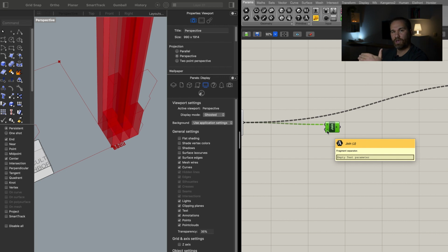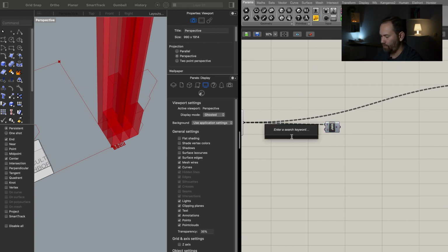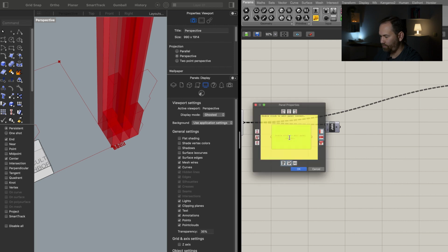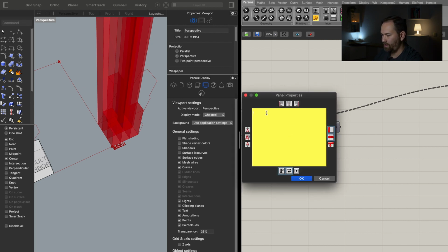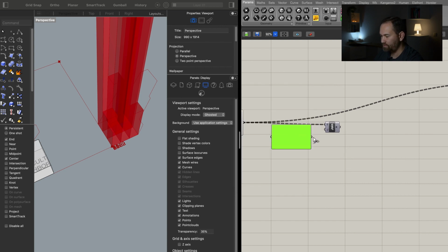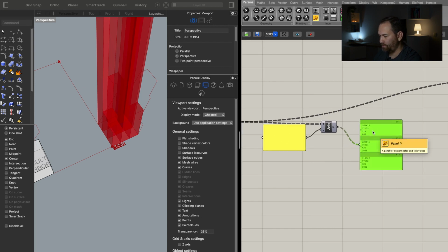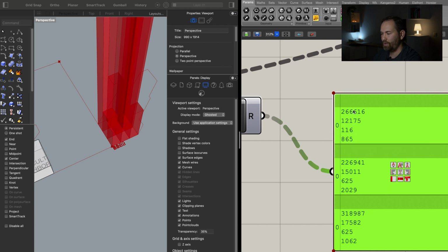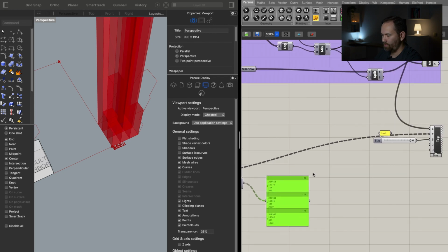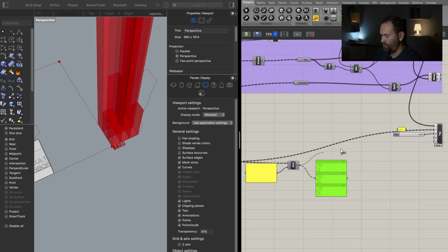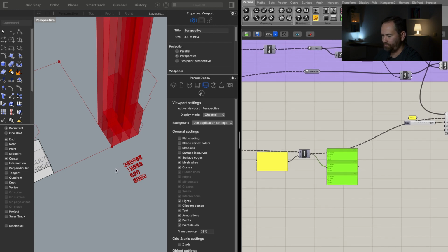And we want to have them on separate rows. So I'm going to bring in a panel, and the panel will contain just a new line character. So I basically pressed enter once in that box. Let's preview what we have. Let's get in another panel. It is what we want. We have one item with an index of 0, but the text is in 4 rows. And let's connect that to our text component.